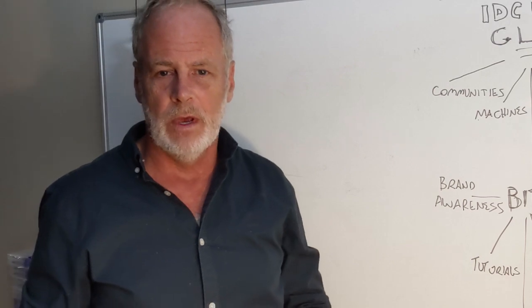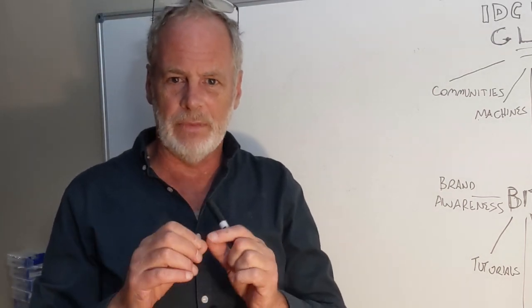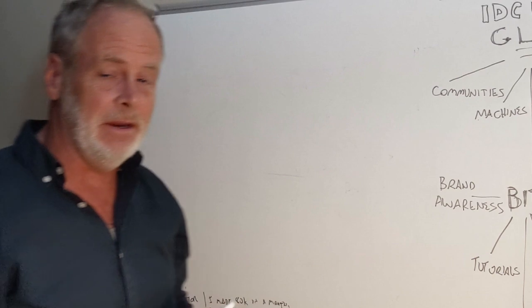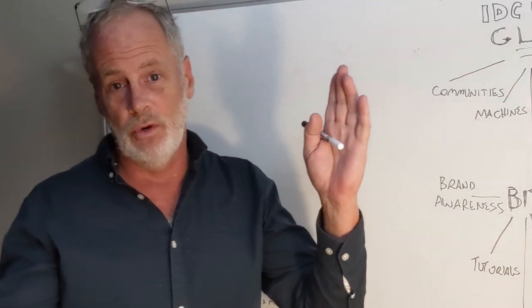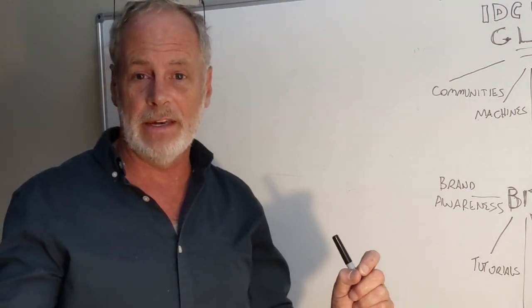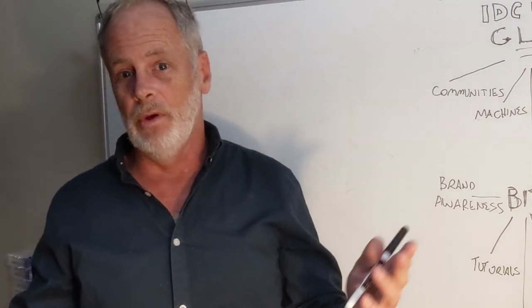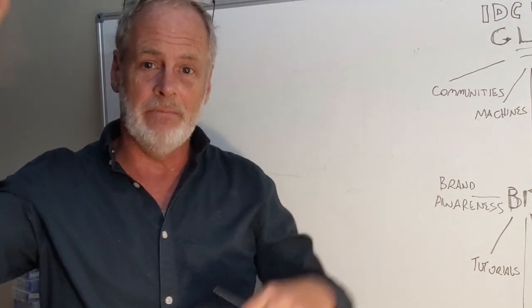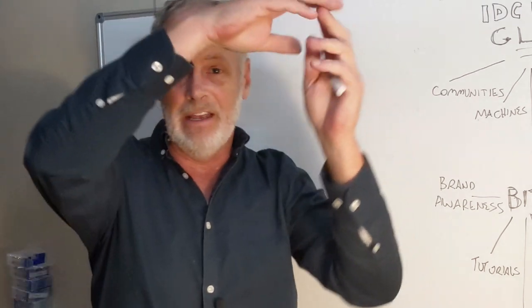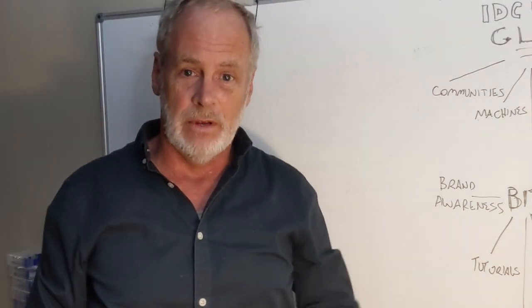So remember, it'll build out from the center if you have the center dot selected. It'll build up and to the right if you have the lower left dot selected. And it'll build down and to the left if you have the upper right dot selected. If you have the upper left dot selected, it'll come down and to the right.